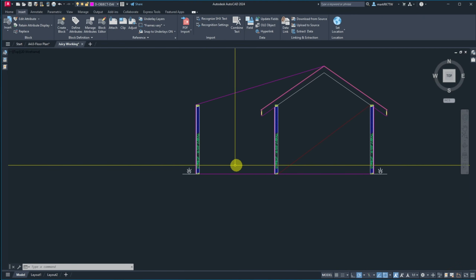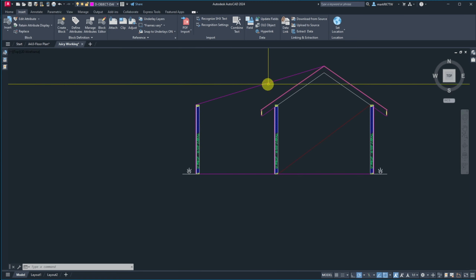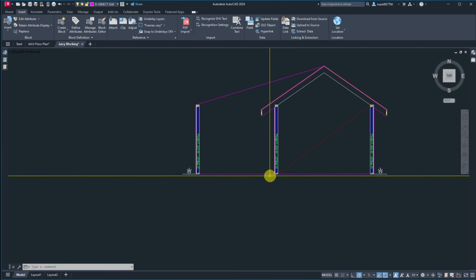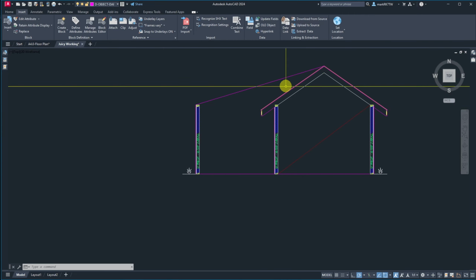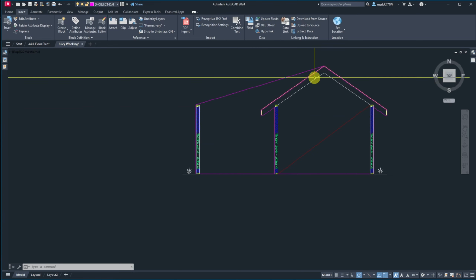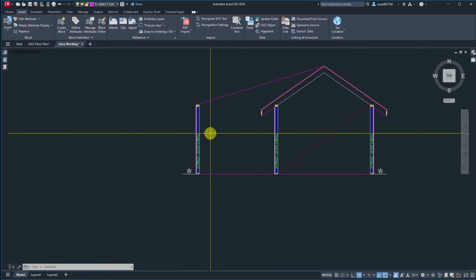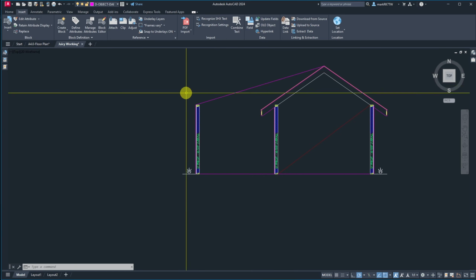And it's possibly going to be quite stout, because when it comes down to the actual structure, I don't believe this has a proper foundation, so I don't think we'll be able to bear on this. This will have to be an independent structure with a cantilever. But we'll get to that more once I've done the inspection of the building and understand it better.